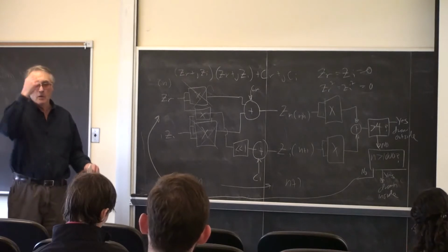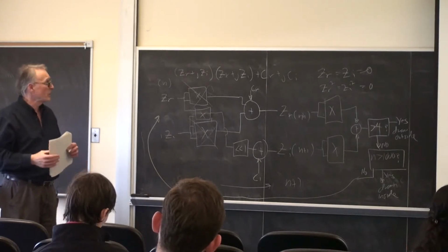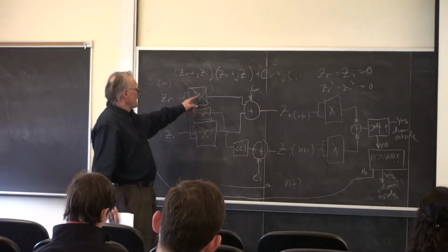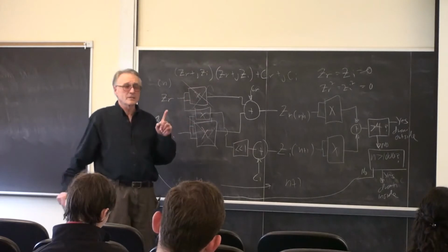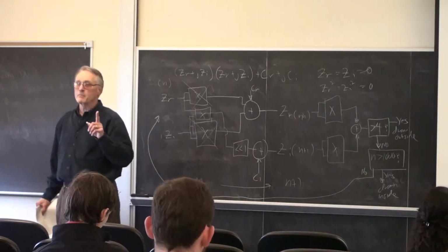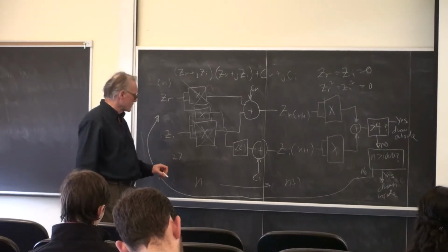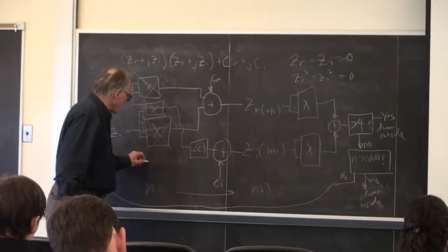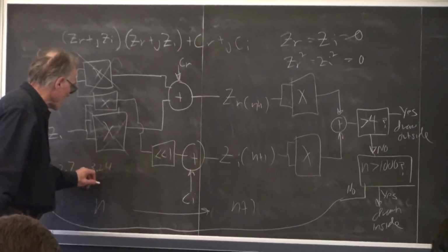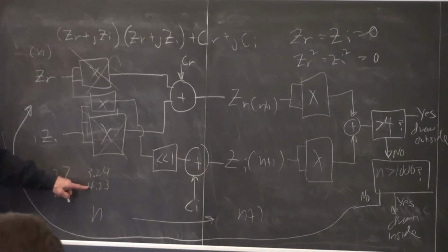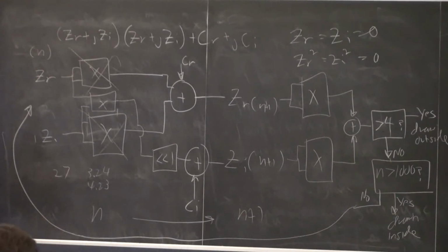So let's say that you decide to use 27-bit multiplications here. Each one of these multipliers will be exactly 1 DSP block. So for 27-bit, which sounds reasonable, you could do, say, 3.24 or 4.23, depending on how much you worry about overflowing this. And you still have 87 multipliers.